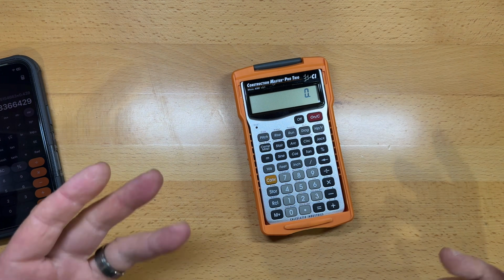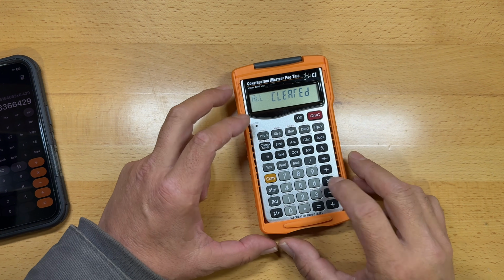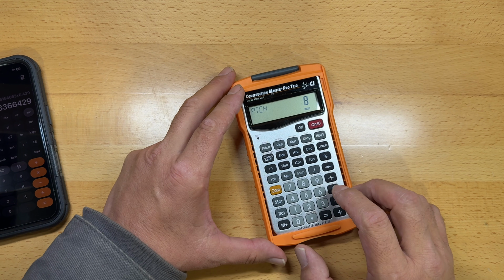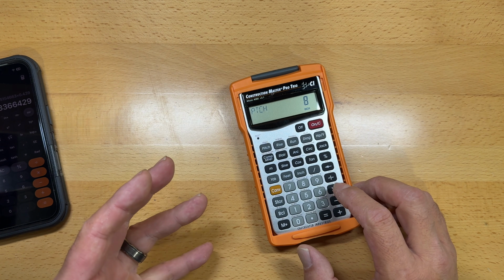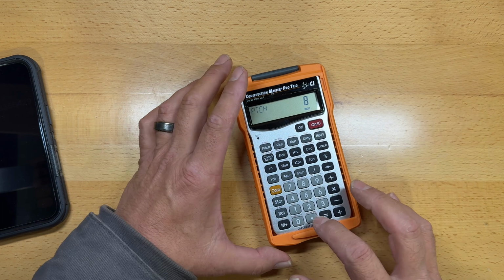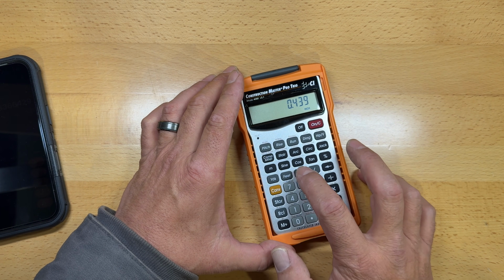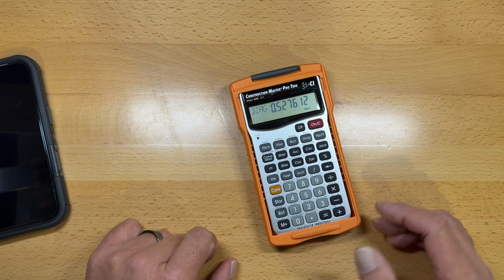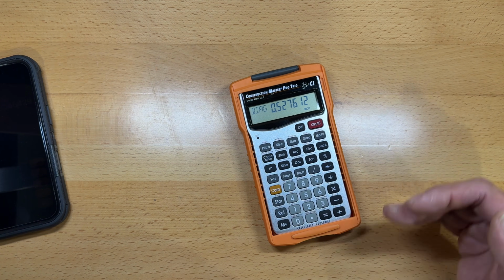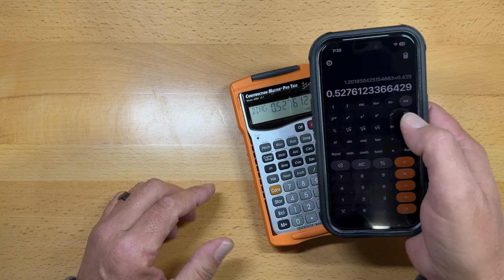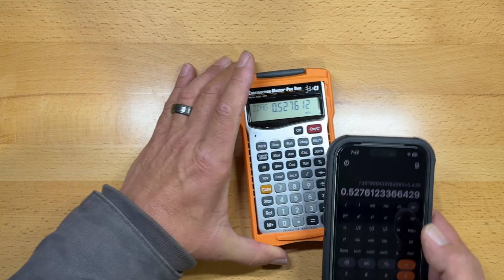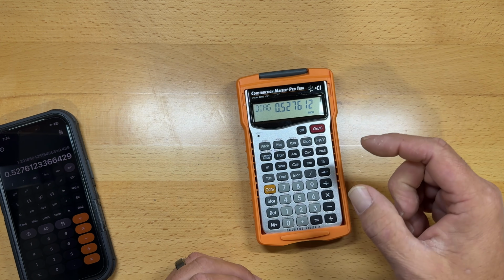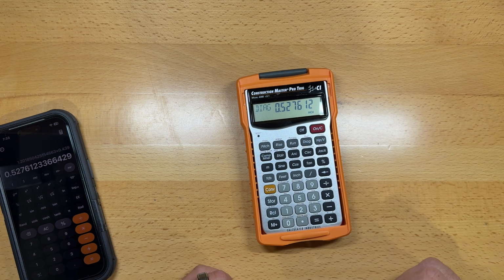Now you can also do this in the construction calculator. So let's clear this out, and we're going to set our pitch the same, 8-inch pitch, and we're going to set our run to 0.439 inch run. And then we hit the diagonal, and we get the same number, the 0.527612. And I believe that should be exactly what we got on our calculator. So you can do it with either calculator. Just change your run to 0.439, and that will tell you exactly how much longer the first jack rafter needs to be.